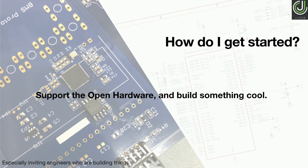But it turns out that the critical path can be optimized. We just haven't done it. And so far as the Sky130 is concerned, the problem is really the tools. You don't have the choice of doing individual blocks. You would do the ALU, you would do the register file, you would do all that stuff separately. But the OpenLane flow or the DARPA OpenROAD flow doesn't really have the capability to put those blocks together except in one great big massive amorphous blob, right?